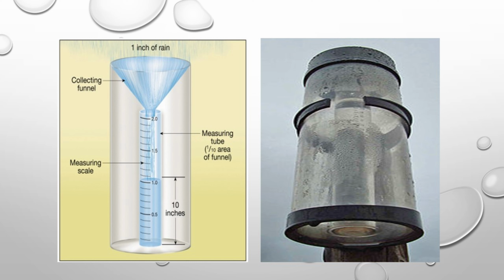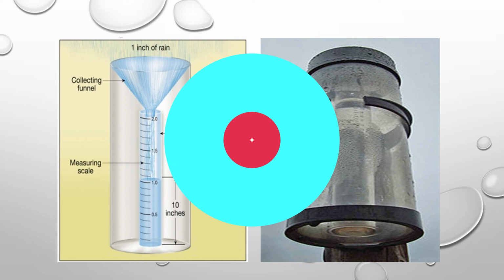Rain passes from a collector into a cylindrical measuring tube inside the overflow can. The measuring tube has a cross-sectional area of 1/10 of the collector, so that 2.5mm rain will fill the tube to 25mm depth. A measuring stick is marked in such a way that 1/10 of the centimeter depth can be measured. In this way, a net rainfall can be measured to the nearest 1mm.